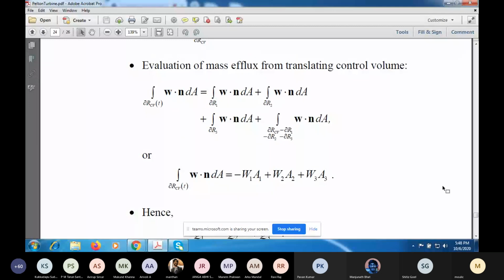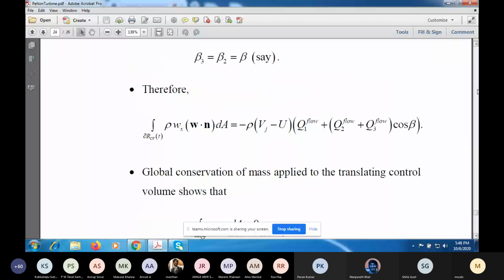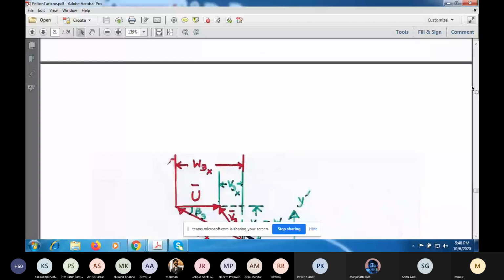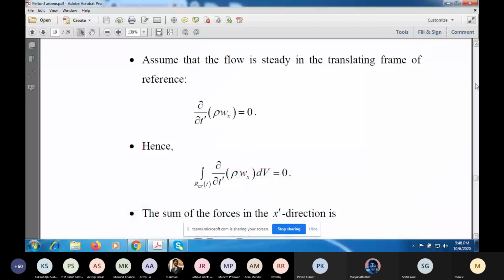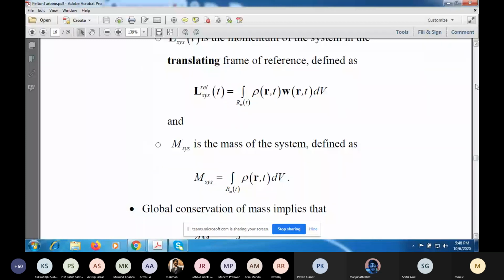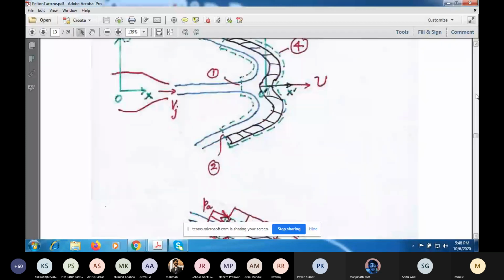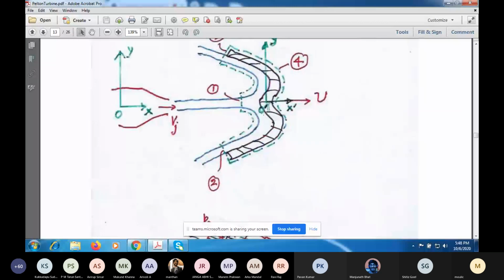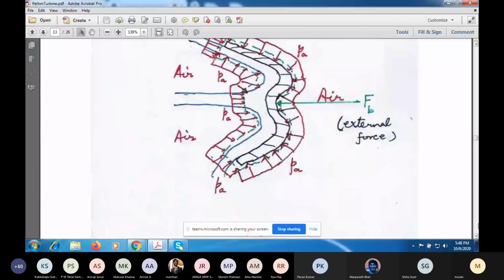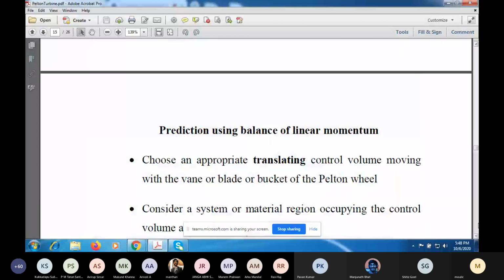Since the density is constant, if you go back and look at the control volume, the volume flow rate of water entering is equal to the sum of the volume flow rate exiting through Q3 as well as Q2. Because the density is constant, no mass can accumulate inside the control volume. So the liquid will be pushed out here. So the sum Q2 plus Q3 then is Q1.